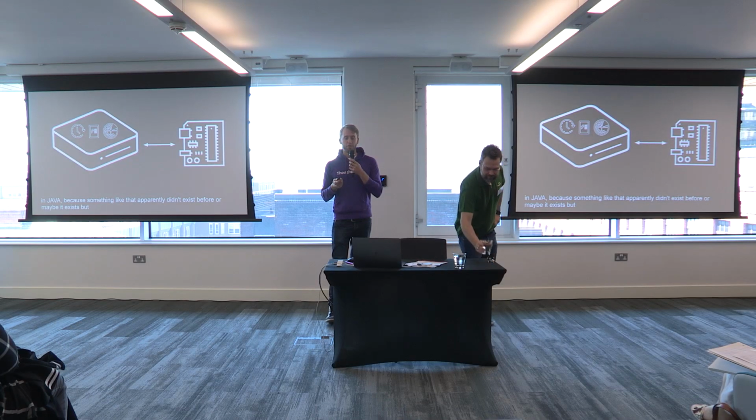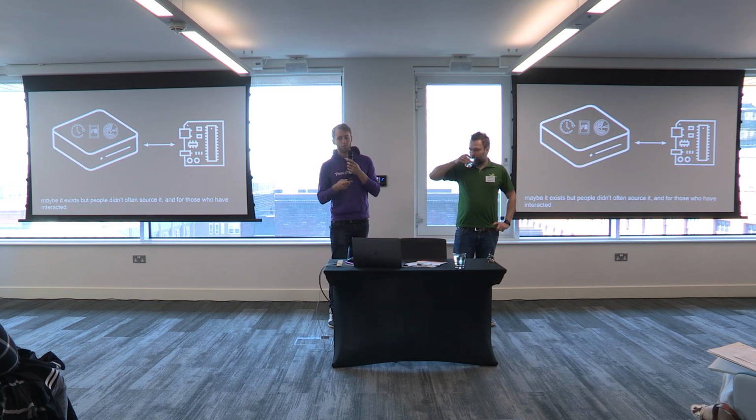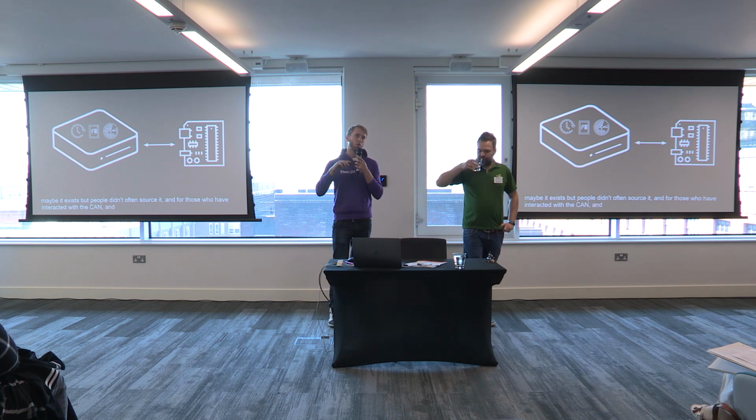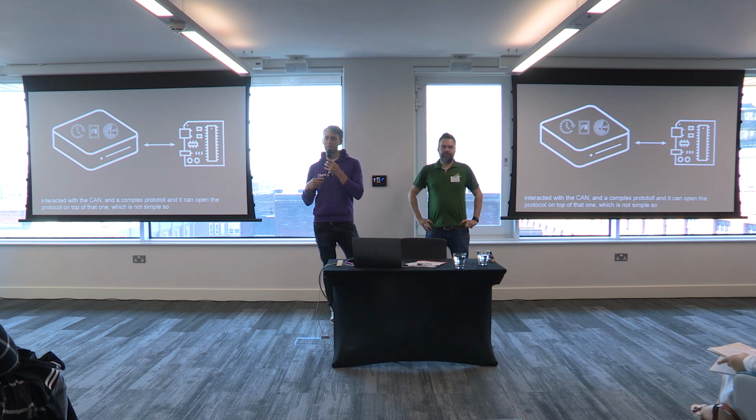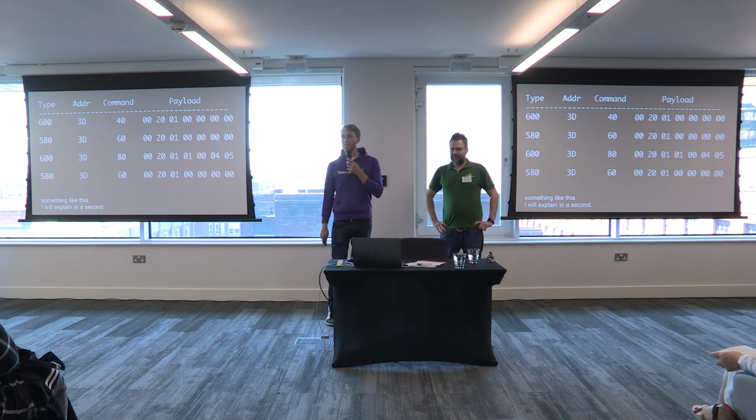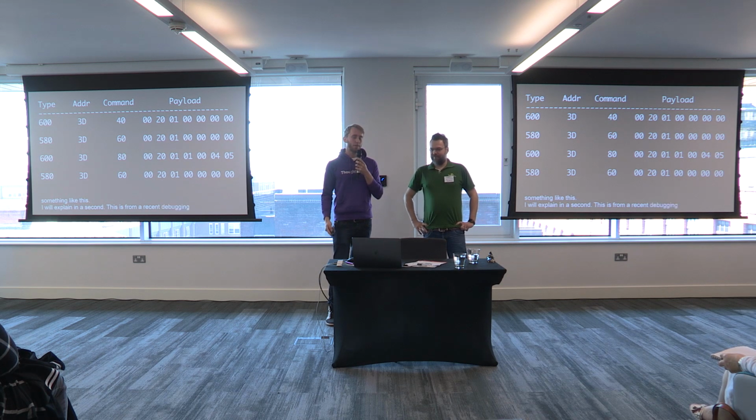For those who have interacted with CAN, it is a complex protocol, and CANopen as a protocol on top of that protocol is also not particularly simple. So implementing this was a lot of back and forth and finding out the corner cases of how everything works. I think the only takeaway for us in this case is if you want to test things on the CAN layer, you should plan a bunch of time for this, because in the end you'll have to write the CAN and CANopen code yourself.